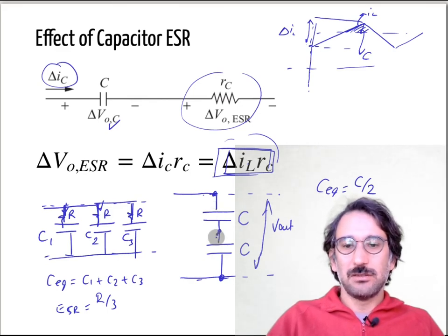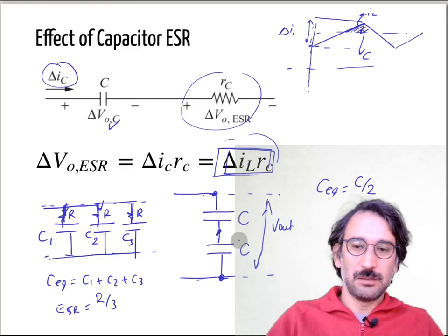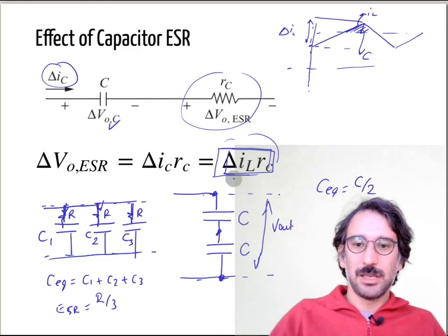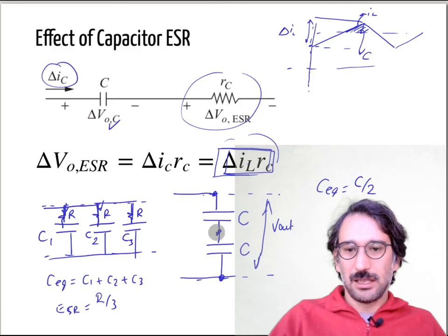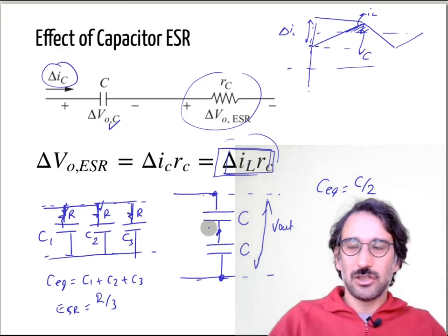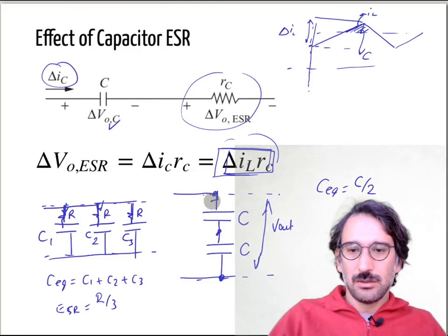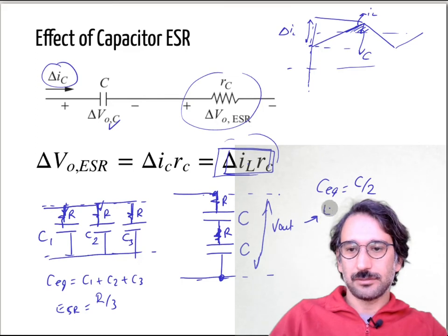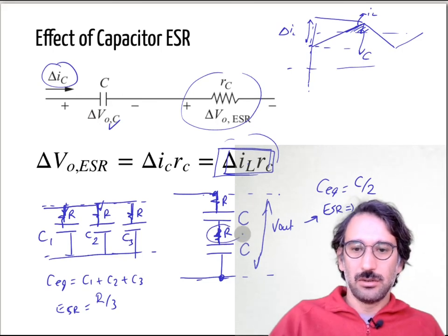But again, you shouldn't assume they will share the voltage equally. The voltage sharing problem between capacitances can be a big problem, and sometimes they connect large resistances in parallel as damping resistors, or in some cases there are active charge control circuits. But anyway, if you have ESR resistances here, now you see it is twice R. So it actually gets worse: even if you increase the voltage rating, you are reducing the capacitance.